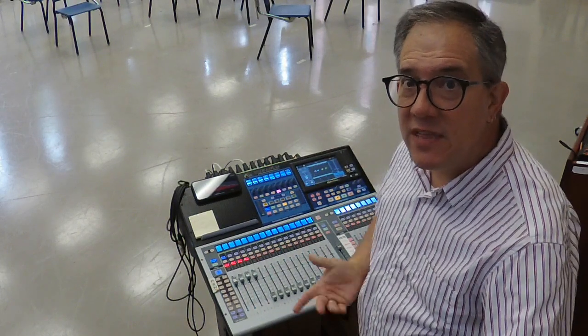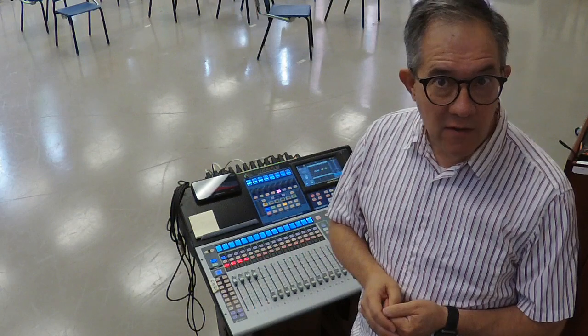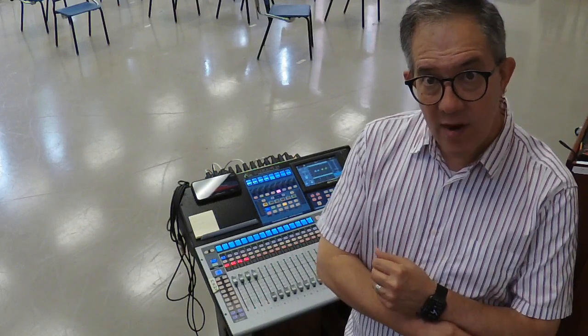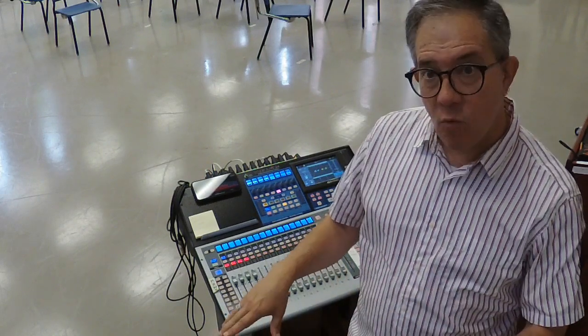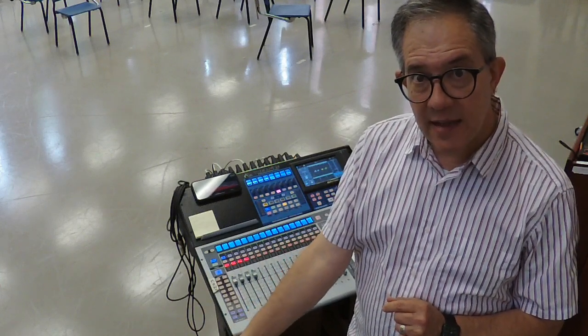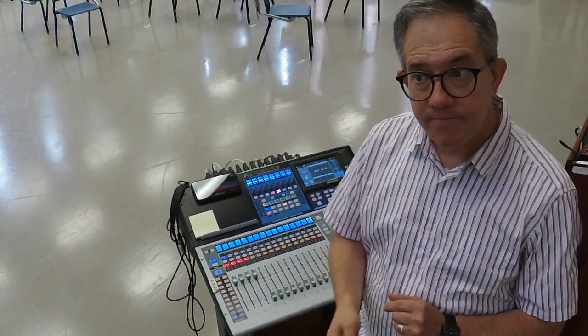There are really three things that go into creating feedback or causing feedback problems. First and foremost is bad positioning of speakers and microphones. If my main speakers for an auditorium are behind where the microphones are placed, they are routing signal into those microphones, and that will cause problems. Likewise, if I have live wedges, monitors on the stage, and an instrumentalist sets the mic down and points it at that monitor, it is likely to cause feedback.